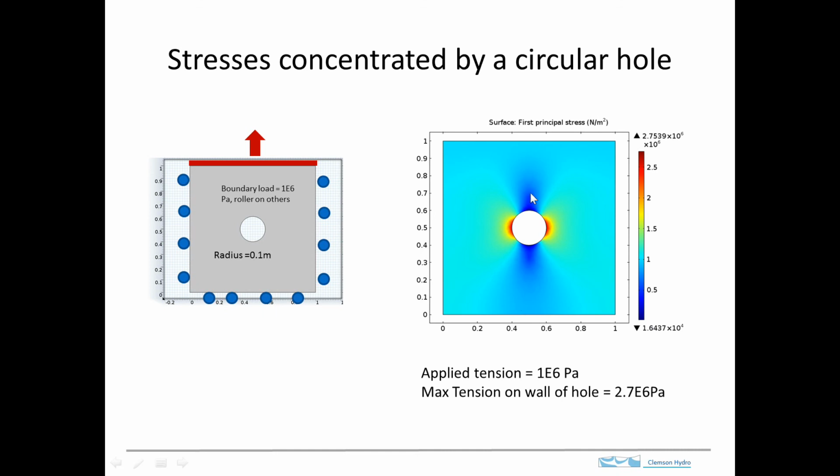And so what's happened is, when we pull on this, think of this maybe as a plate with a hole in it. When we pull on this plate like that, we cause an increase in the tensile stress right here and a decrease right there.